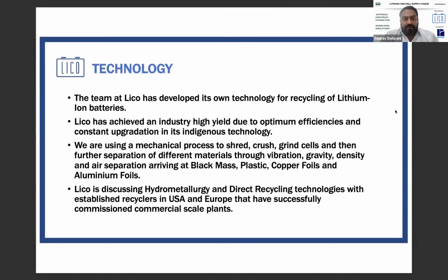Regarding our technology, the team at LICO has developed its own technology for recycling lithium-ion batteries. We have achieved an industry-high yield due to optimum efficiencies and constant upgradation in our technology. At the moment, we are using only the mechanical process, which is shredding, crushing, grinding cells, and then further separation of different materials through vibration, gravity, density, and air separation, so that you arrive at black mass, plastic, copper foils, and aluminum foils.